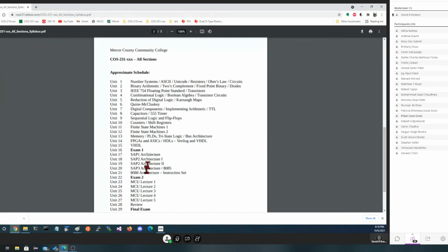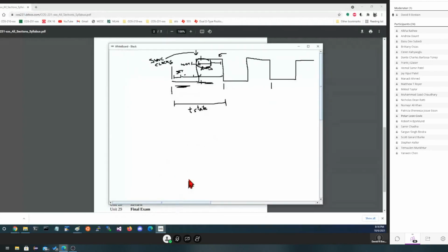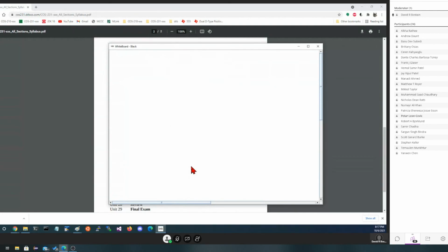Okay, well, we actually have 4 minutes, because that's probably going to be enough for me to give you a start on the schematics. In general, we draw boxes which have function as squares or rectangles. In the case of a latch or a flip-flop, we're normally going to put the outputs on the right-hand side. So we might have Q, might have not Q.